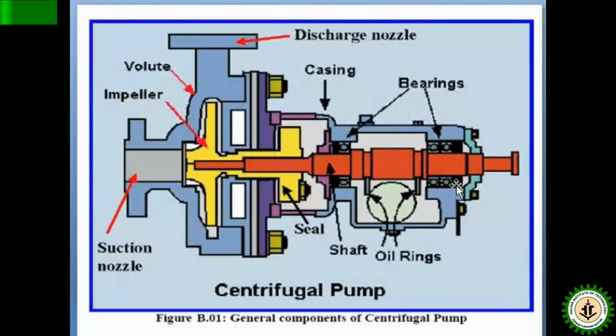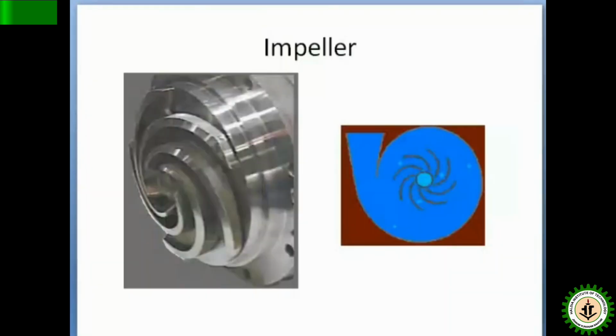And this is the nozzle and bearing. Why is the bearing there? Because the bearing helps the shaft rest in its position while rotating. Otherwise, this impeller will touch the casing. This is the mechanical seal, this is the oil seal, for lubrication. So these are the basic purposes.